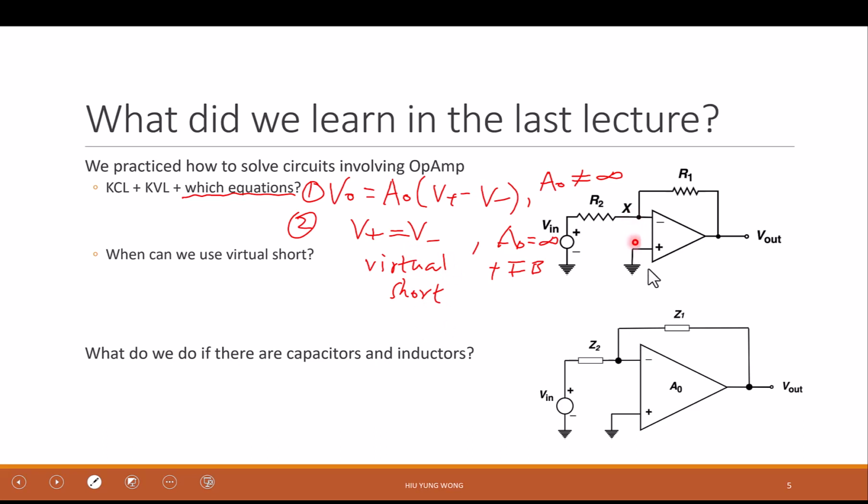Okay, for example, here, I give you this circuit and you can assume it has a proper feedback. Of course, you need to check it later in principle, right? But you can trust me, I'm not going to trick you. But when you're doing your real design, you need to be careful it has this proper feedback. When the gain is infinity, the V out is going to change such that it's going to force this point to be almost the same as this point. And that's why you can assume V plus equals V minus.